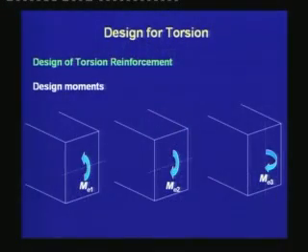Thus, if the torsion is substantially high, then we may need to design for the other two equivalent moments ME2 and ME3 that will provide us designed longitudinal reinforcement at the other face.